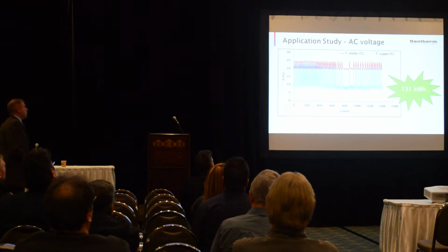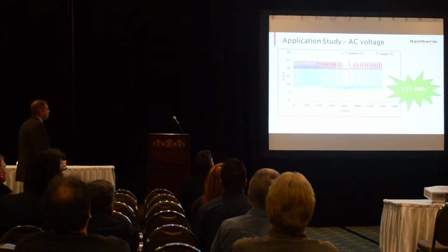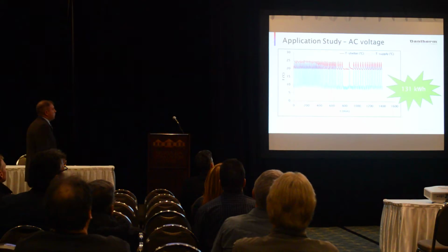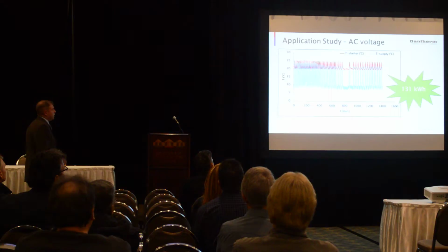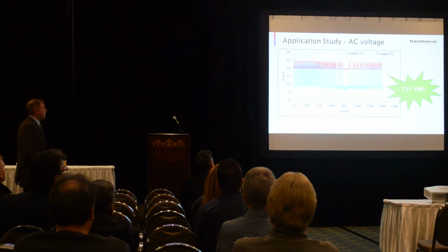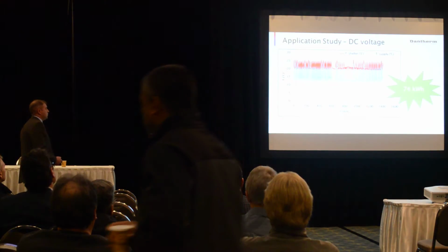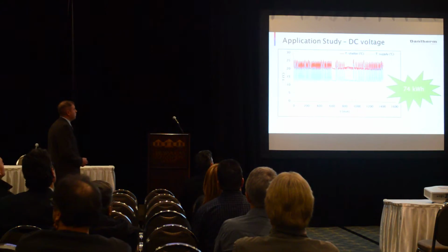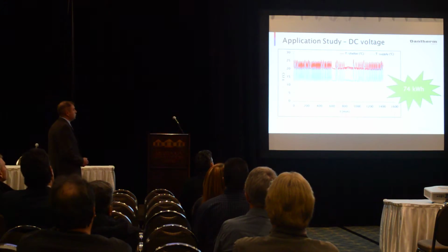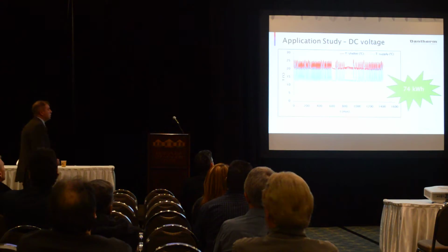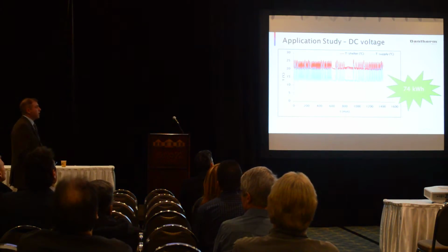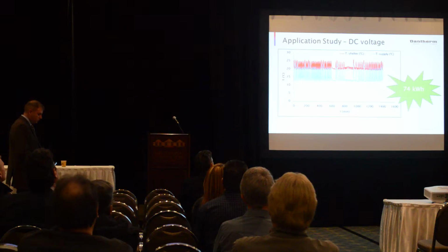So we put each in graphs. You can see the set point here. So you're getting 7 or 8. Look at this, look how big this gap is, not to mention the surge up, down, down, down. So that's not a very tight temperature control. So 7 to 8 to 25, as you can see, going constantly. DC, this is the DC on off, not the capacity control. It's getting a little bit tighter. So it's 12 to 13 up to the set point. And that tightening of the gap is where you get your savings that we showed before in the previous slide.